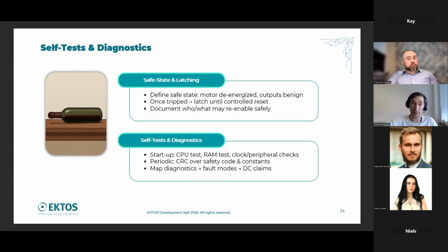And also, of course, software implementation gives you a lot of limitations. Just imagine if you need to check your RAM and it does not have incorporated measures. You have to go region by region and check that all cells, all bits are okay, there is no intersection, and it is quite heavy to do.